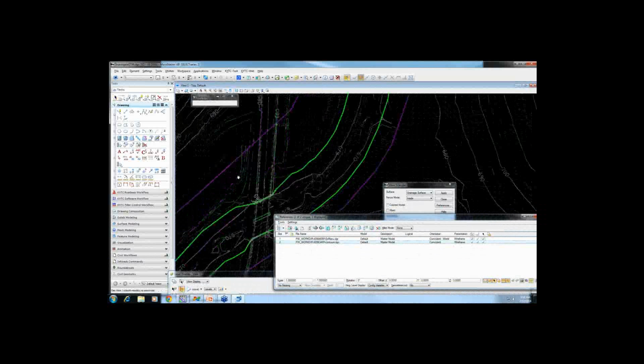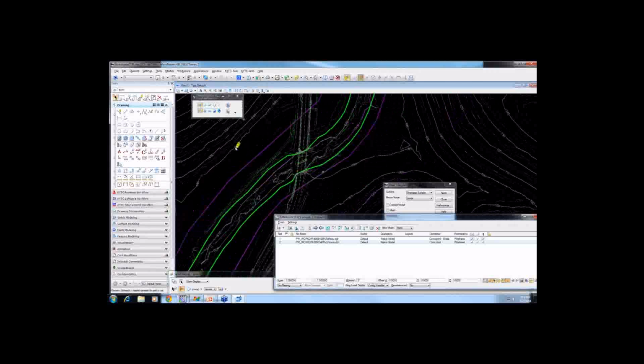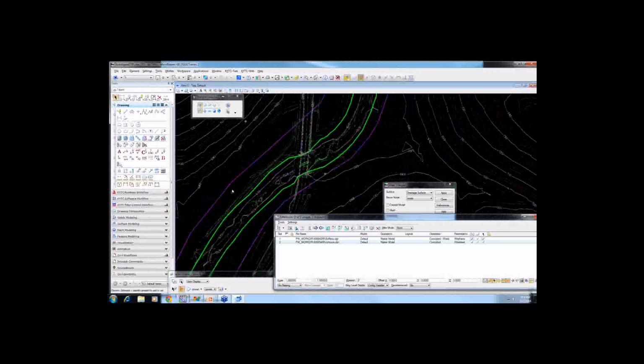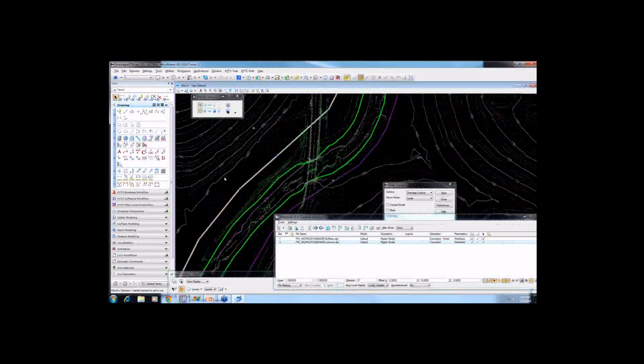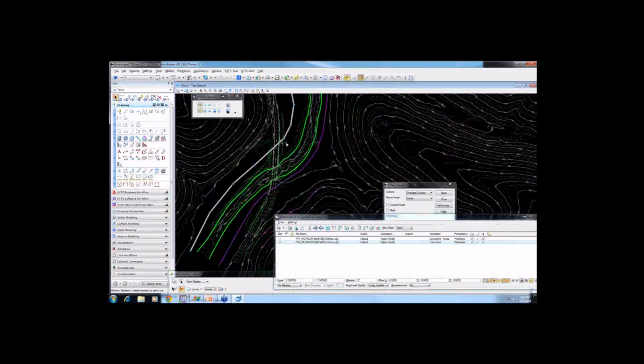So this purple line, water gets up around 682, I think, on this project. So I've just got this purple line placed roughly between the top of bank and 680. But you can see how many vertexes I have. I'm not getting crazy here with every 10 feet having a vertex. This is just given the downstream reach length between the sections that we're going to end up drawing.